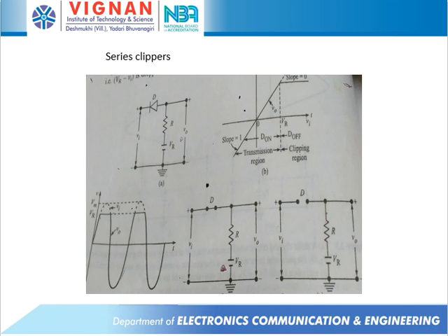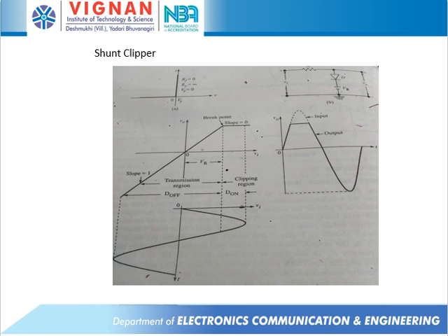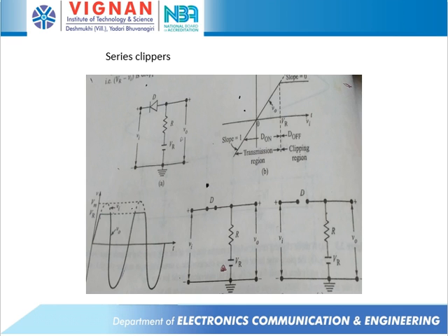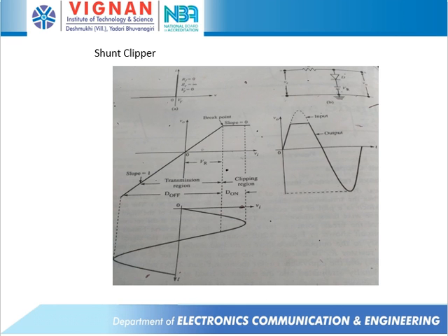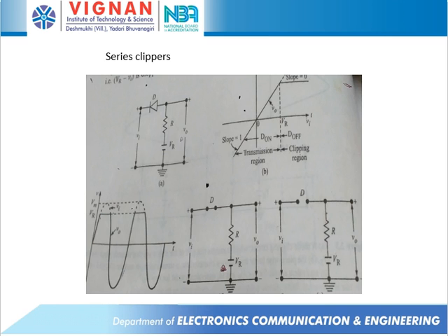Similarly, if you observe our series clippers, you can clearly observe the structural difference between this shunt clipper and series clipper. In the shunt clipper, we place our diode in shunt with the output. In the series clipper, we place our diode in series with the output.